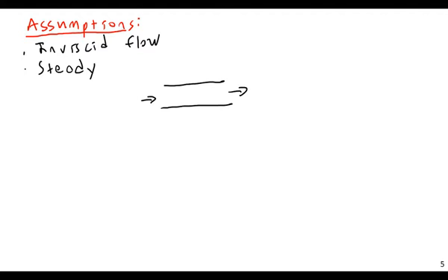And so you hear that kind of gurgling, you hear all those bubbles being formed, a very turbulent condition. Water is mixing with air, and the water is quite rapidly, in some cases, forcing the air out of the hose. That's a very turbulent, violent kind of process, and we can't model that with something as simple as a simple equation like Bernoulli. You can't make exact predictions, so you can't actually model it even using more finite element type models, but that's beyond the scope of this course.